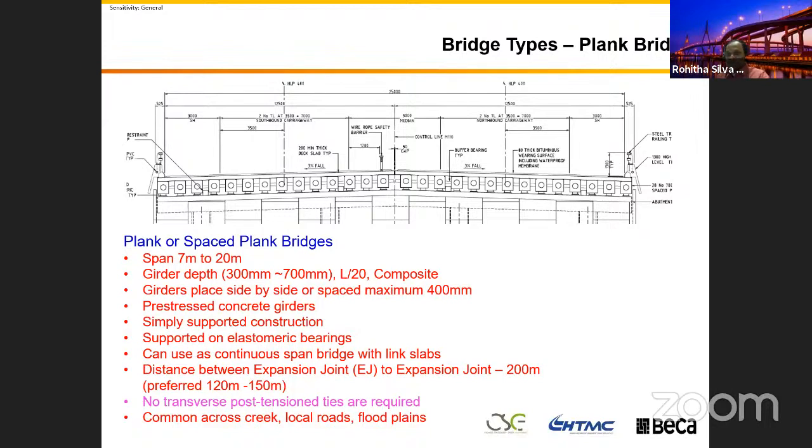There are a lot built in Australia without this tie, because this tie is one of the most difficult things to construct and maintain. And there's no guarantee with this, with the fatigue and things, whether you get a crack or not depends on the quality of the tie. That is what I want to emphasize in this bridge design. That is one of the main advantages. You can use the plank without having a tension tie, which is really good, because I know how difficult it is to build this one, from my experience in Bangkok.